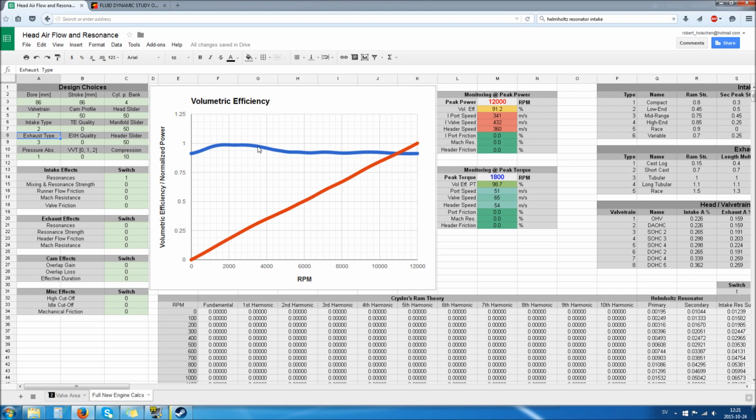And that is used in economy engines, especially smaller engines, which have a pretty high frequency, meaning higher RPM, to shift down the peak of resonance into an economy-relevant area, and that would be around 2000 RPM, where you do your cruising. So if you have a really small engine, you run into the problem of these resonances being further up, as you can see here. And this is now, even with intake 2, already in a range where you actually lose a bit of efficiency between 1500 and 2000 RPM. You peak around 2200. It's still good, but if you go to a mid-range intake, you will see, nope, that definitely doesn't really make eco work anymore.